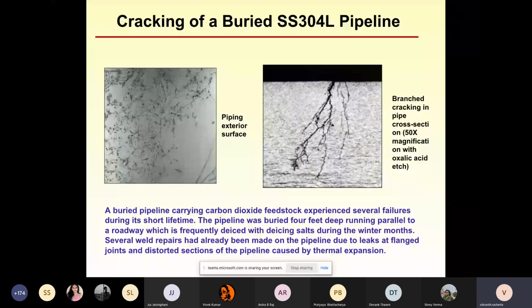It's mainly residual stress created during manufacturing itself. We tend to think that only external loading causes stresses within the material. Many a times the manufacturing process itself creates a large amount of stress within the material. So if you do any sort of a welding operation, or if you do any cold forming operation, it results in very large amount of stresses within the material, which far exceeds anything that you generate through external loading. So these internal stresses can result in this stress corrosion cracking.